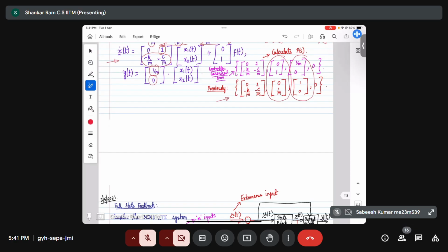But controllability is a physical property of the system. It doesn't matter whether you do transformations to make the state matrix diagonal or it remains non-diagonal. It's an inherent property of the system. You and I cannot change controllability just by doing transformations; we can study controllability by doing transformations. But a system is either completely controllable or not completely controllable. Transformation is not going to change it.